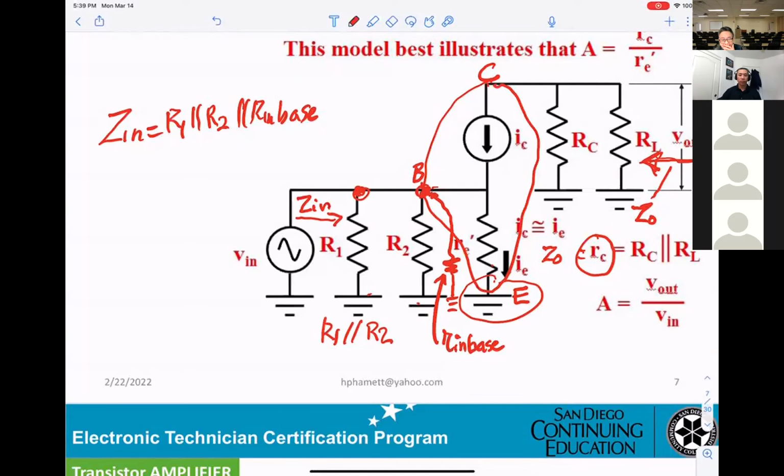However, input impedance is another case. For input impedance, you get the input right here. You're looking into the amplifier. Try to see how many resistances are in series or parallel. Try to combine them. Okay. First thing to see, R1 parallel R2. However, you still get one more resistance that you didn't see here. That's what we call R in base.